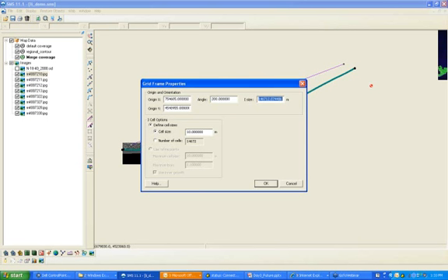And what I should mention is when you create your grid frame, the reason I'm changing the locations of my origin X and origin Y is because these are cases we've already completed. When you start setting up your own case, you probably will not need to change your X and Y coordinates. You may want to change your angle just so it's an easy number instead of, in this case, I've changed it to 200.